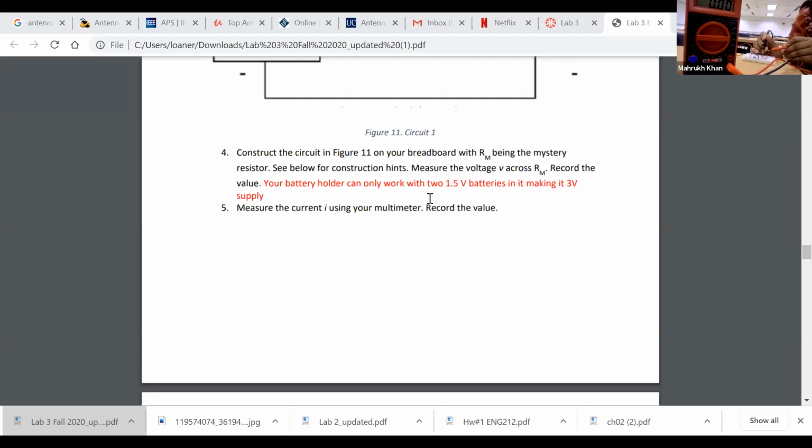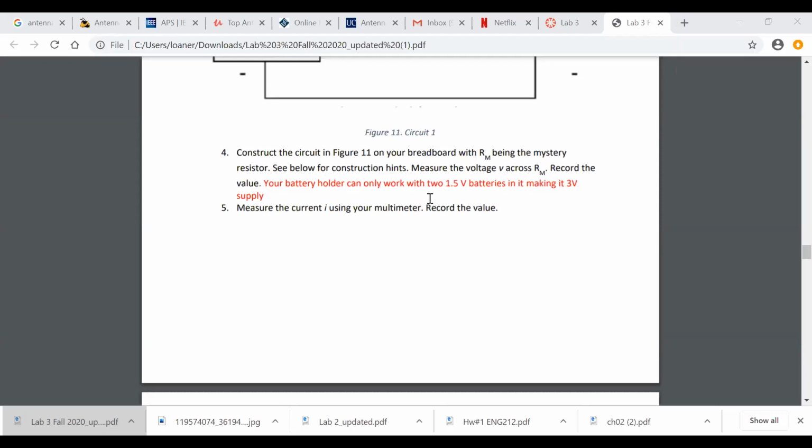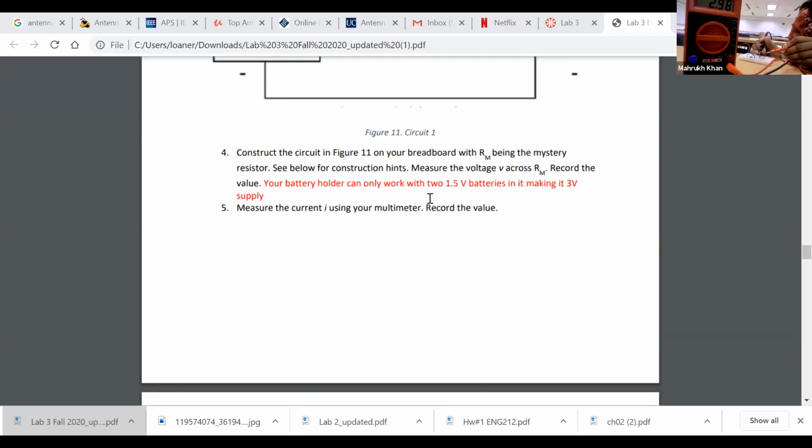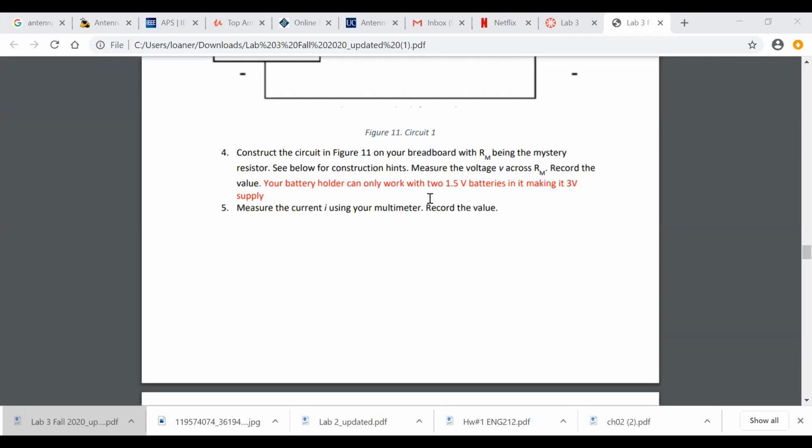Okay, so you can see 2.99, right? 2.99, 2.98, right? Yeah. So that's how much current is flowing through that. What unit is it set to right now? It's like 20 milliamp? Yes, 20 milliamp, which means that it's giving me milliamps. So it's 2.9 milliamps. Okay. Gotcha.